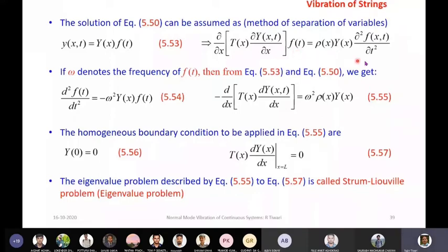Now this equation will separate the time-dependent terms on one side and all the x-dependent terms on the left side. And as we did for the beam case, because on the left side only spatial coordinate terms are there, and on the right side we have only the time-dependent component, if we bring that to this side, then they will be equal only when both are equal to some constant, and that will be a negative constant. I think this should be 0. This will not come.